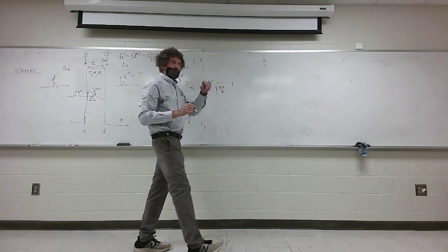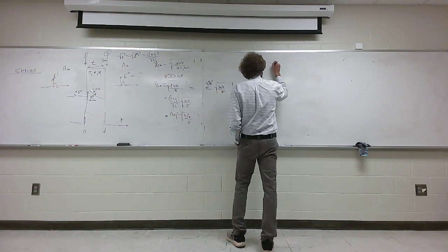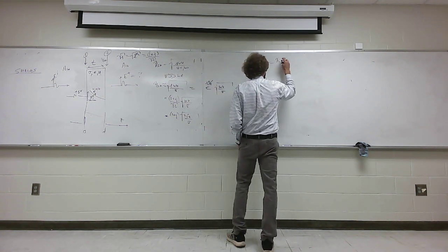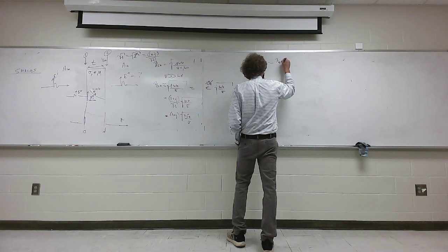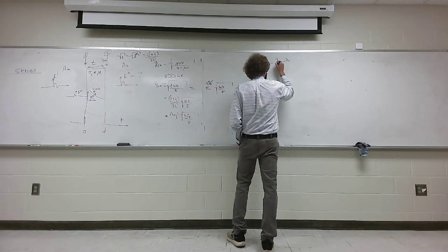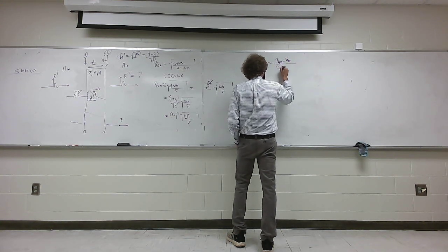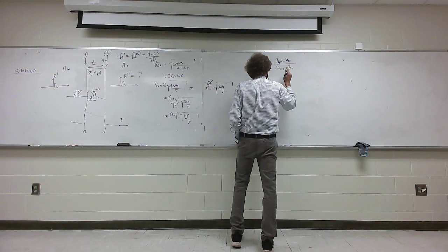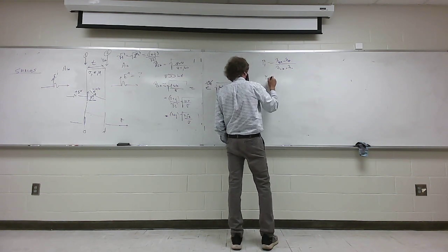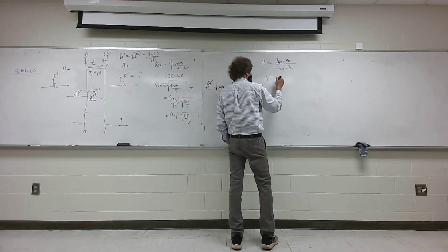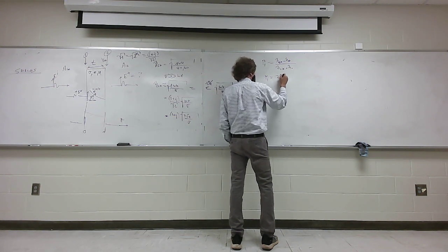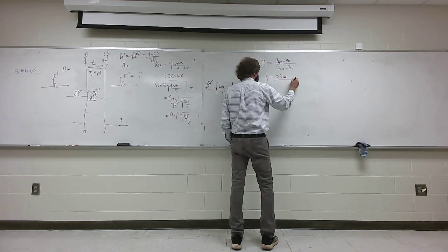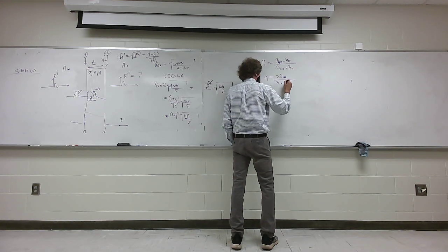And I can say the reflection coefficient at 1 is simply eta 2, or eta shield, minus eta naught over eta shield plus eta naught. And I could take a look at the transmission coefficient at 1, which would be equal to eta shield over eta shield plus eta naught.